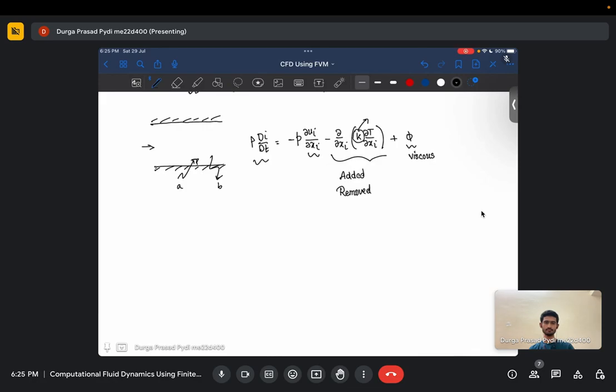It's the conduction, right? What I was trying to ask is, this entire differential equation is for a fluid element, right? The equation is derived for a fluid element. So for the fluid element, the internal energy change should be equal to some heat term and some viscous dissipation term. Your internal energy can increase either because of these two.